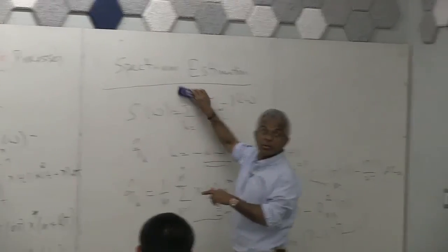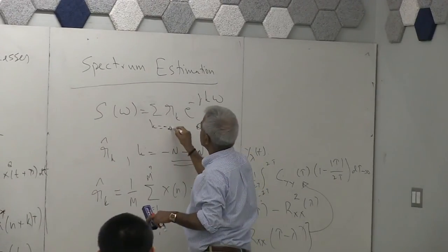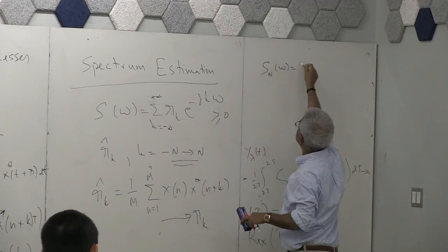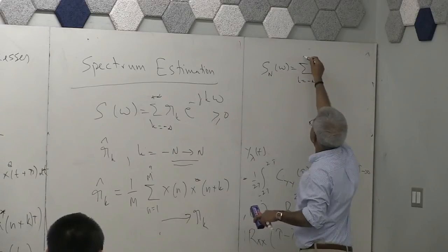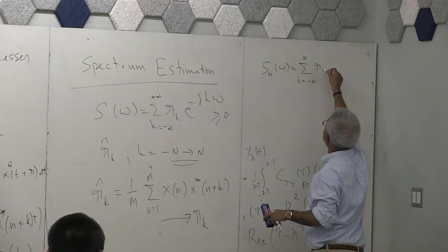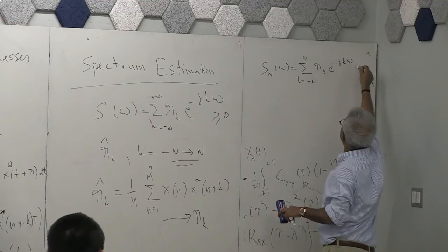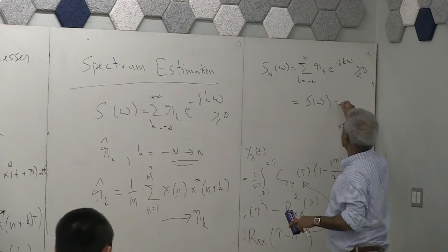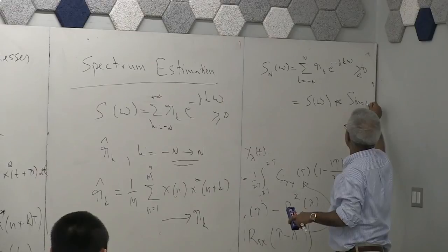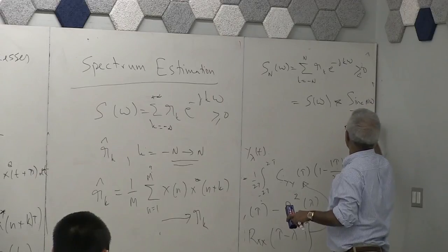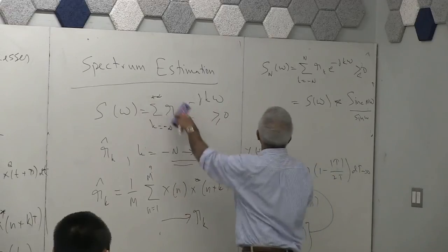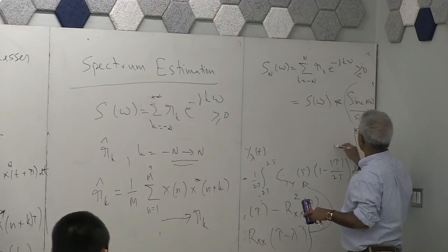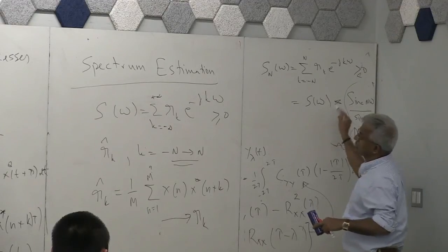positive. This is of course positive. What I'm trying to say is that if you use n samples, this may or may not be positive. Because you can show that this is the convolution of, you're only using a window here, right? So this is as good as multiplying by a sinc window, and that sinc window could go positive and negative. So this is a bad idea.